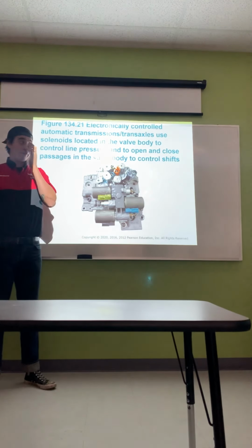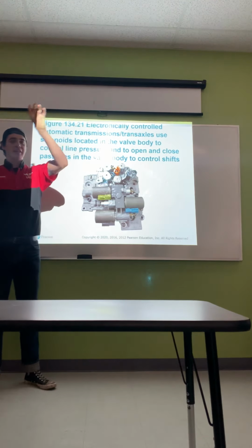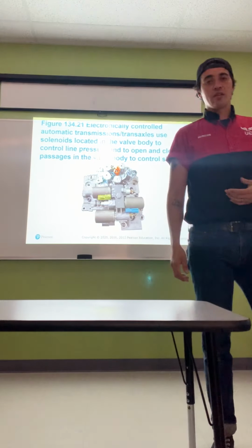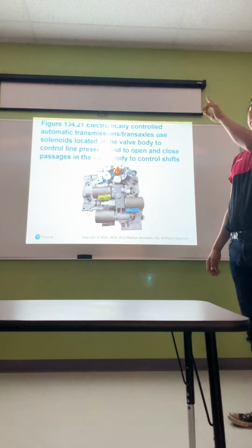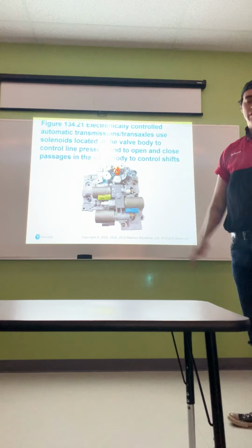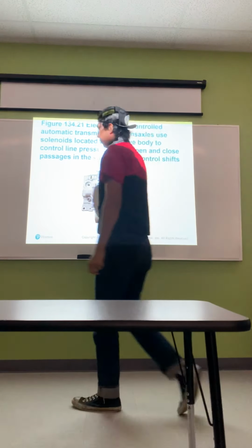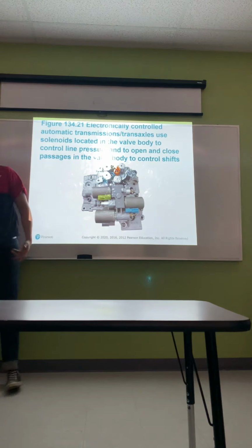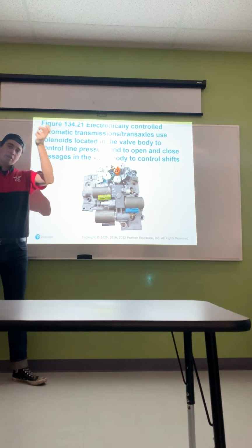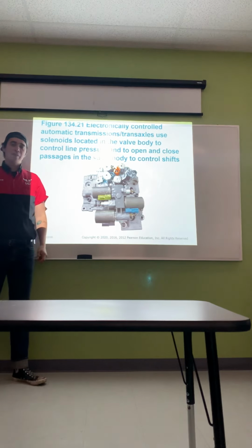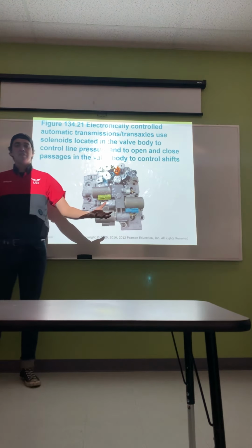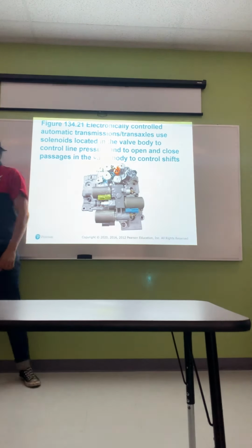I did one on a Ford, I believe. Their solenoids are actually on the outside. The 1-2 shift solenoid, so from first to second, went bad, so I went under there, found out which one it was, disconnected it, put in a new one, test drove it, it was fine. So some of these can be replaced without tearing into too much. Some of them you have to drain the pan, pull the pan off, replace the solenoid because it's on the side of the valve body, and put it all back together. But it's still a lot better than having to blow apart an entire transmission for a $40 solenoid.